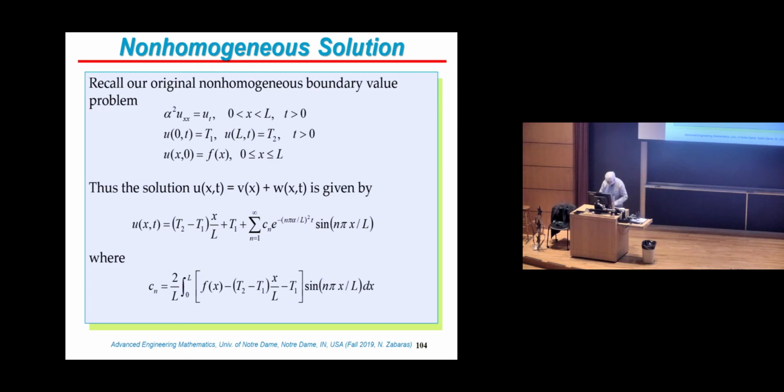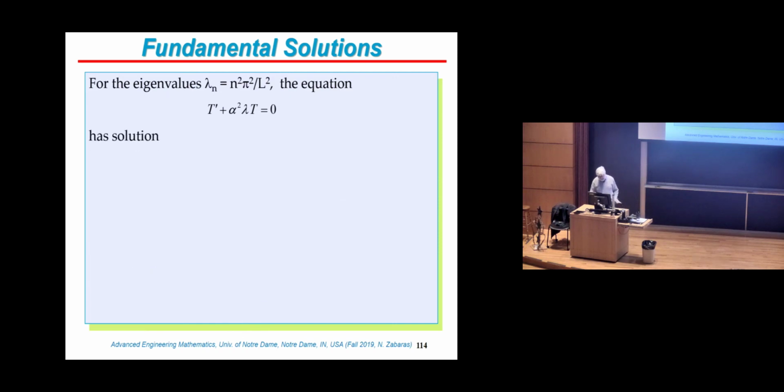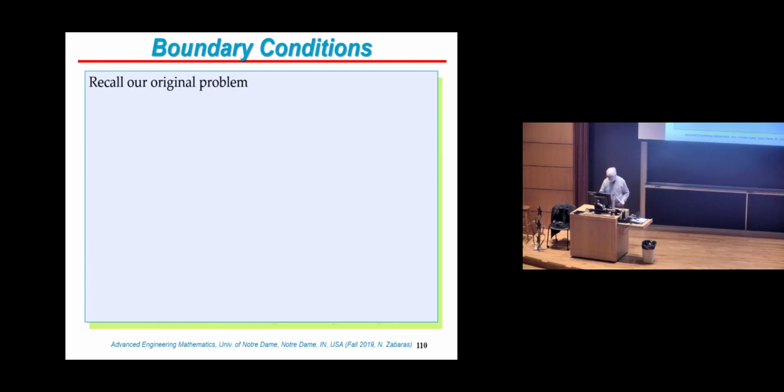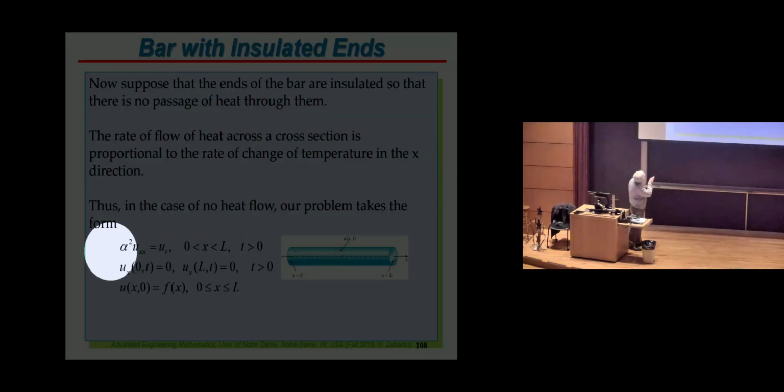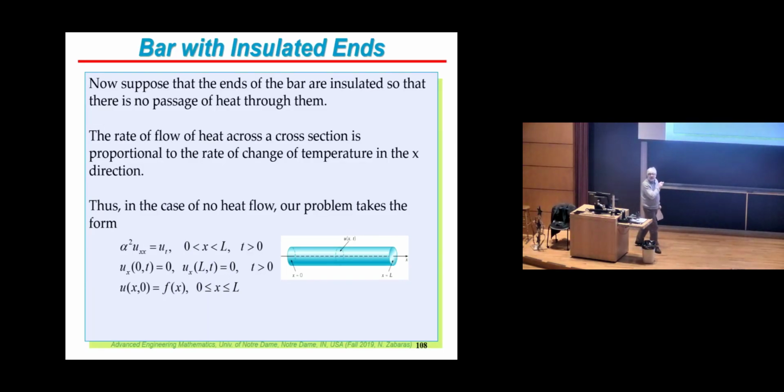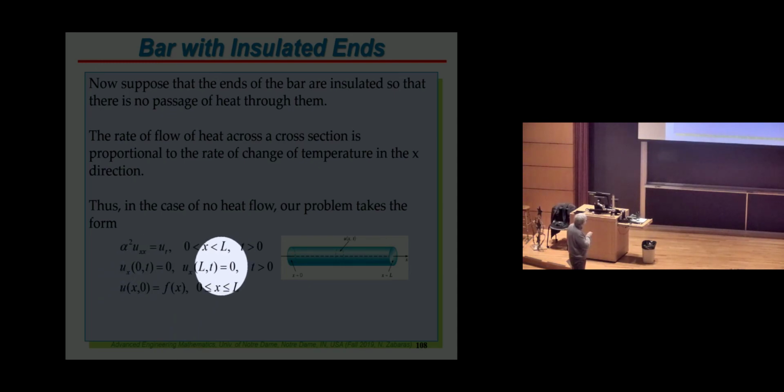Something with a gradient, you said, right? So you may have boundary conditions given in terms of flux, right? So you don't want any heat in or out at x equals 0. You don't want any heat in or out at x equals L. And you remember the flux is minus k times the gradient of temperature, but right now we do mathematics. So heat in and out, we write in terms of the derivatives of x, right? So those two derivatives have to be equal to 0.